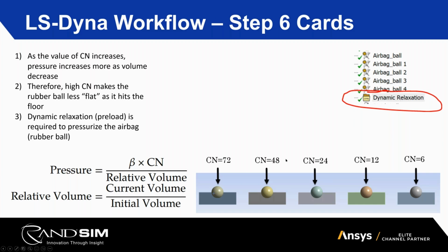So why is that necessary here? It's because before the ball impacts the floor, I'm going to have to tell the program to inflate the ball, and that has effects that we have to understand. Because you are introducing load into the system, in a dynamic analysis, things start vibrating. So we want to make sure before we start the analysis, we're minimizing the kinetic energy in the entire